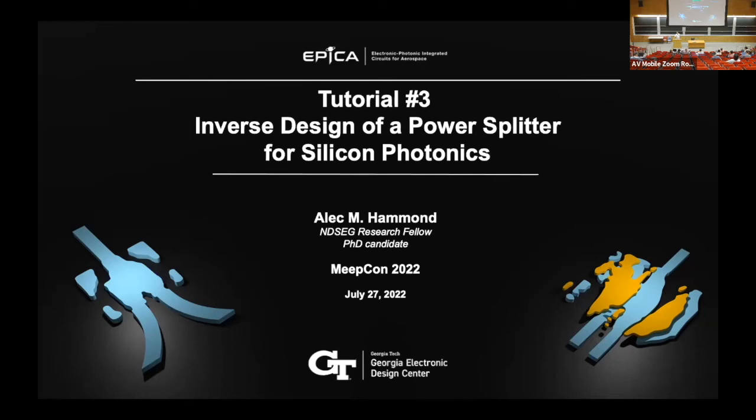I think this is not due to binning. That's not how this works. It's not like if you add more frequency points, then somehow it's changing the definition of the Fourier transform at those points, like it's doing some filtering. We're not filtering it and then integrating the whole thing in some frequency bin, right? In other words, it's not a DFT, it's a DTFT, right?